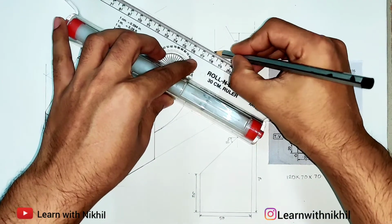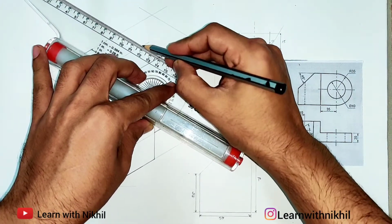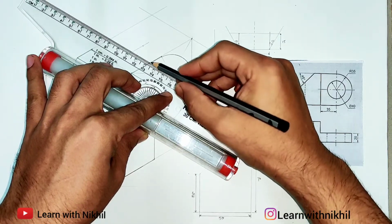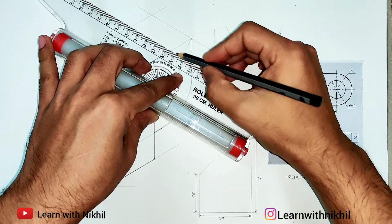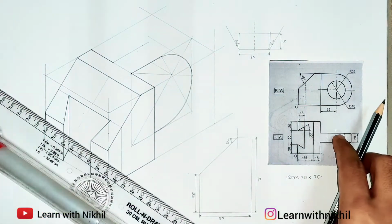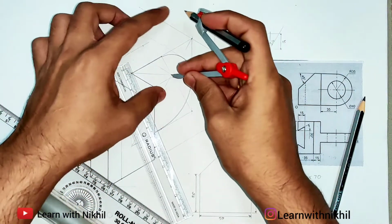Now you have to project the point from where we have plotted on the left side. So I'm projecting this end, the center point, 20 on the left. This part also I'm projecting with a light line. This is already projected. Now the center point, I have projected it 20 millimeters on the left side.